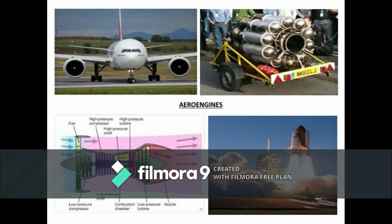Then coming to the turboshaft engine, it is utilized in helicopters. The same turbojet engine will be there, and at the end, after the turbine, we will have one free turbine, connected through a gear mechanism to one vertical shaft, and that vertical shaft goes through a gearbox. It will drive the main rotor blade and tail rotor blade.